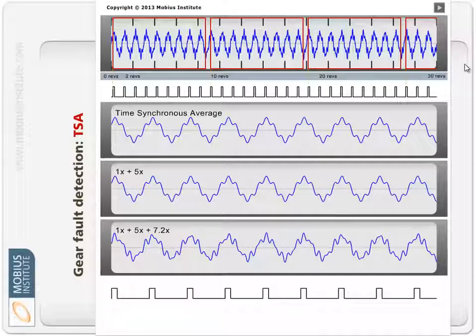However, if you've got a multi-stage gearbox, well, you just averaged away a lot of gear vibration that you are interested in. So now, ideally, you would also get a tack signal off the intermediate shaft, or in every shaft that's in the gearbox. Now, you may not be able to do that, but thanks to the wonders of software and electronics and so on, there is an easier way. You still need a once per rev reference signal that comes from the gearbox. You still need something that tells you, at least for one of the shafts, that you need this one tack signal.